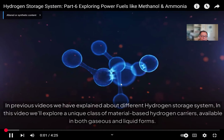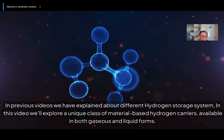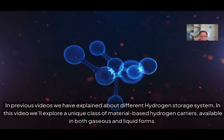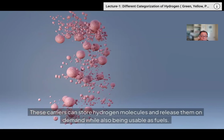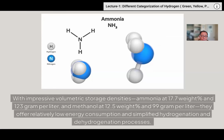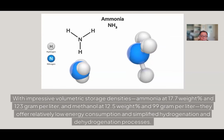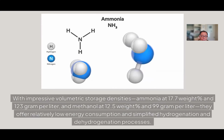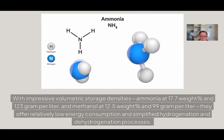In previous videos, we have explained different hydrogen storage systems. In this video, we'll explore a unique class of material-based hydrogen carriers, available in both gaseous and liquid forms. These carriers can store hydrogen molecules and release them on demand while also being usable as fuels. With impressive volumetric storage densities, ammonia at 17.7 weight% and 123 grams per liter, and methanol at 12.5 weight% and 99 grams per liter, they offer relatively low energy consumption and simplified hydrogenation and dehydrogenation processes.